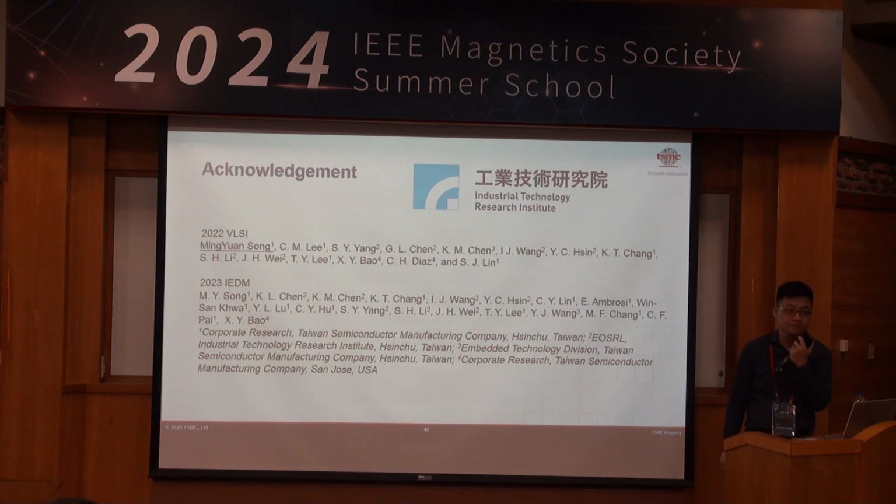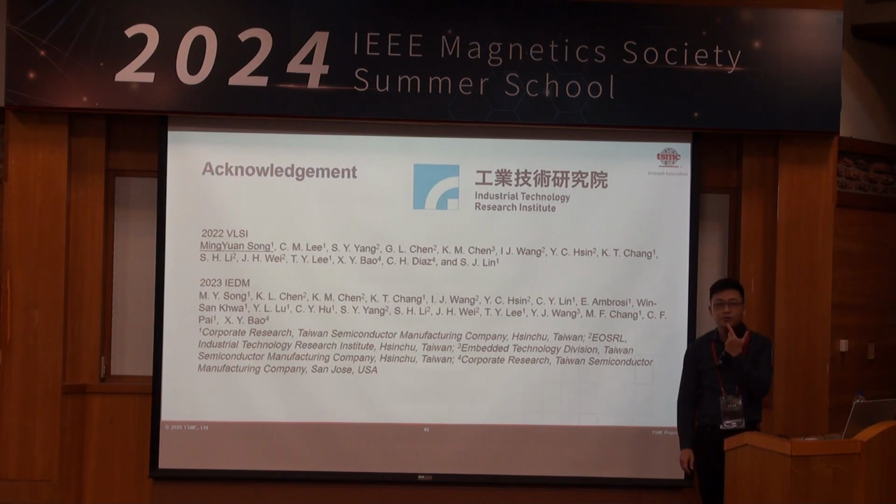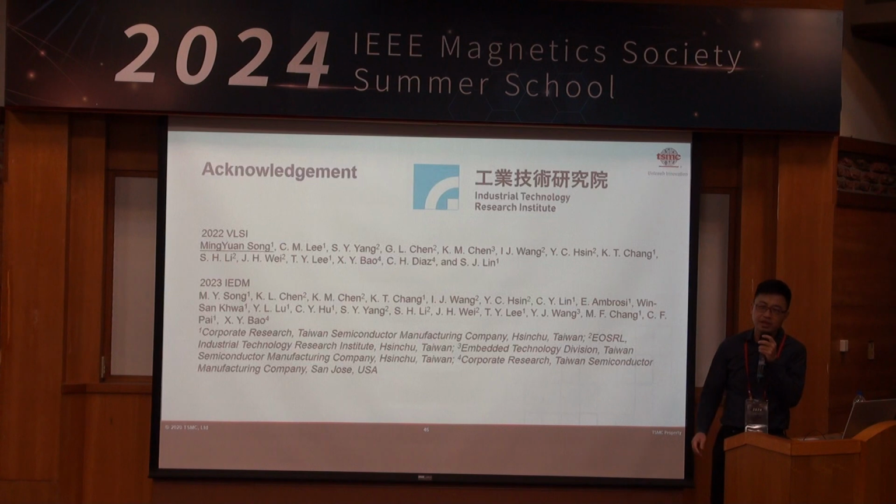What is the effective spin-Hall angle, or the SOT efficiency, of the device? At the very beginning we fabricated the Hall bar structure, and we think it's roughly 0.5. 0.5 is the spin-Hall angle? Yes, the SOT spin-Hall angle. We use the second harmonic measurement.